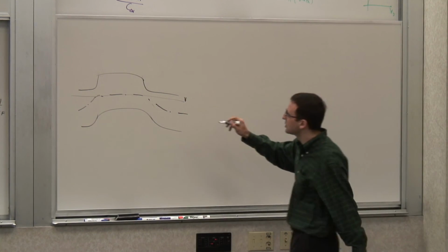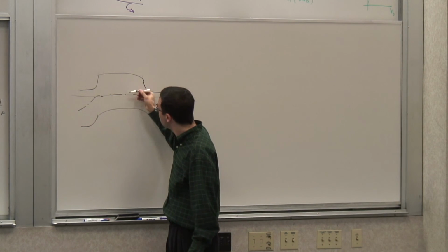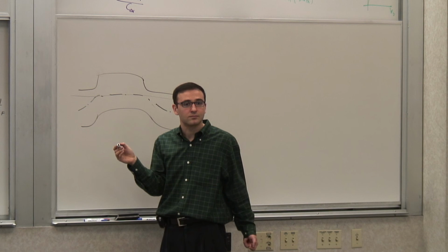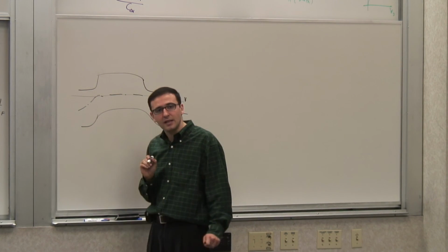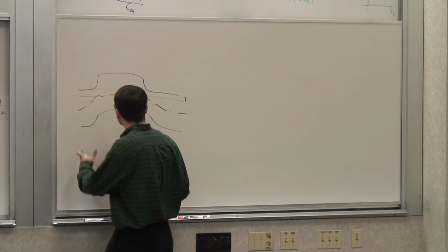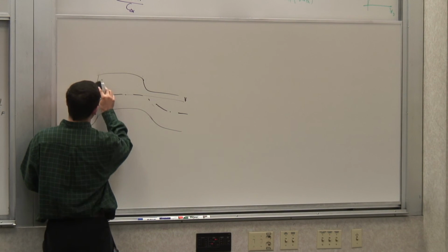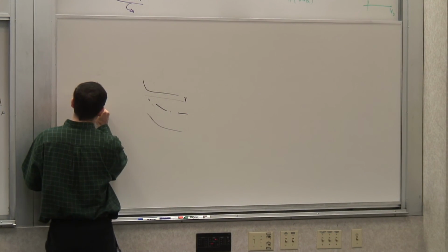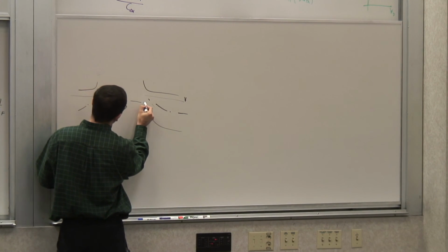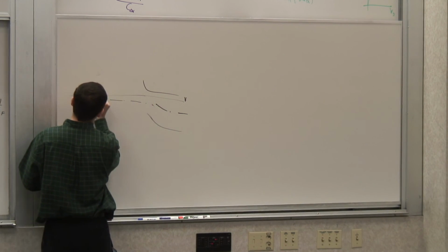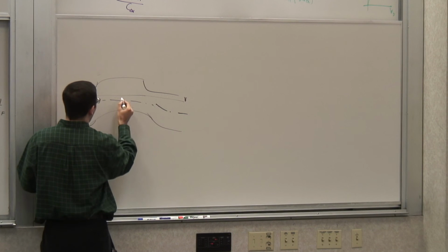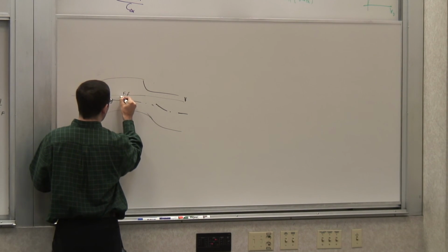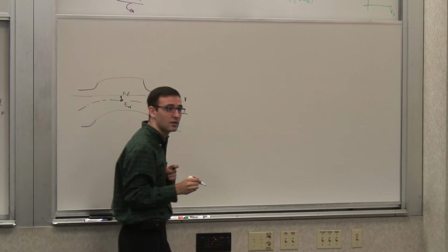But at this point in the channel, if EF and EI are like that, it basically means that it's kind of an intrinsic semiconductor. Right? Anything above this will result. So if I start increasing the voltage, what happens is that I lower the potential barrier a little more, and this will go down. This will go below EF a little bit. Now, this is EF, this is EI. Now I can say I have some excess electrons in the channel.